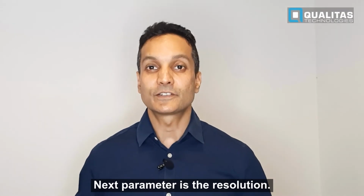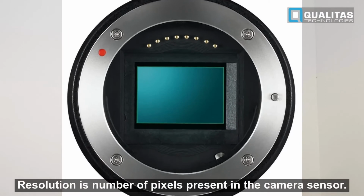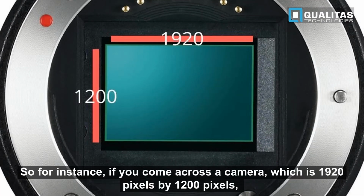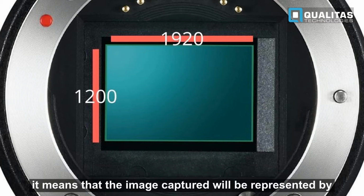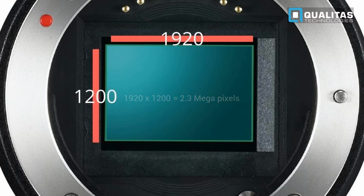Next parameter is the resolution. This is probably the one you've heard the most. Resolution is the number of pixels present in the camera sensor. So for instance, if you come across a camera which is 1920 pixels by 1200 pixels, it means that the image captured will be represented by 1920 into 1200, or roughly 2.3 megapixels in size.